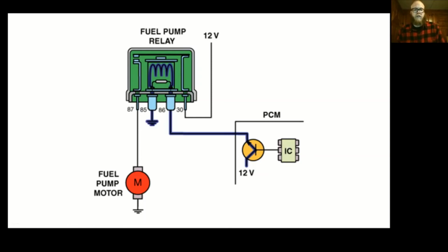It just looks off of accelerator pedal and throttle angle, and it can figure out, well, the throttle's wide open, I need the pump to be spinning all the time, or, well, we're just kind of cruising down a hill, so I can duty cycle this pump motor so that the motor's spinning at 25% of its top speed.